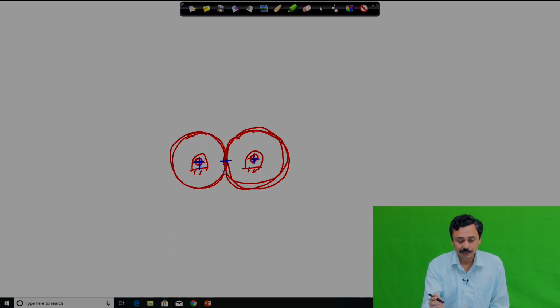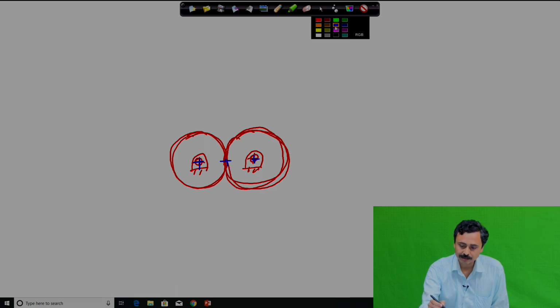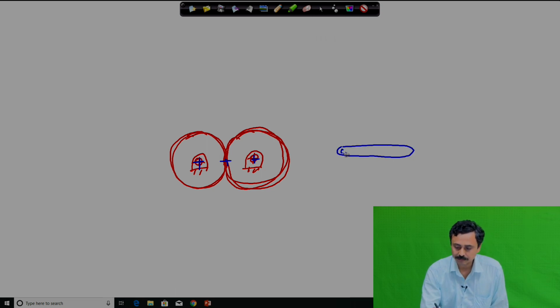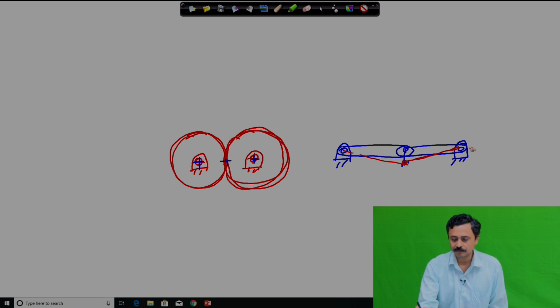Here it always remains, but if you do this with links, if you join this, if you have links like this, you try to move this slightly, this IC will shift from its position, and it will not lie on, this is an exaggerated diagram, it will not lie on the same straight line. So, it will refuse to move beyond a certain point, but there is a little possibility when it is exactly on this line, then there. So, this is actually some kind of a singular configuration.